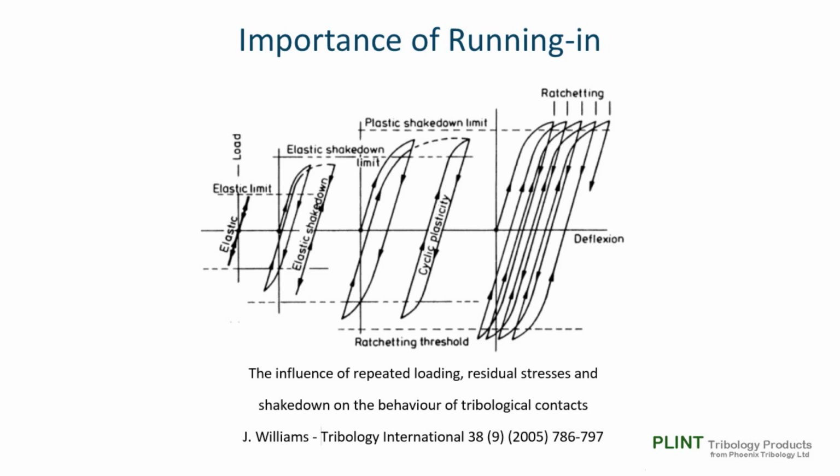At this point, further elastic deformation ceases to be possible, and the material achieves a steady-state running condition, which is a necessary precondition for any subsequent rolling contact fatigue test. This running-in process is referred to as elastic shakedown.